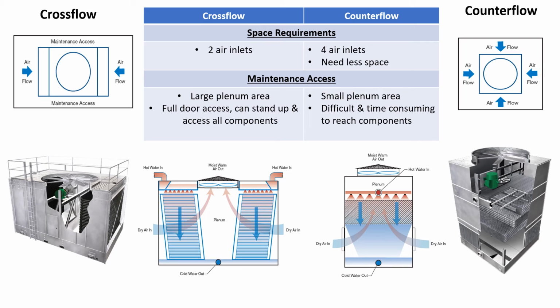The main advantage of crossflow towers over counterflow is the ability to access them for maintenance. This is mainly due to the plenum area for each of the towers. As you can see, crossflow towers have a large plenum area in the center of the tower. There's full door access, which you can see right here, and maintenance workers can stand up completely and reach all of the components of the tower. They can also easily climb a ladder and reach the fan and water distribution decks of the crossflow tower.